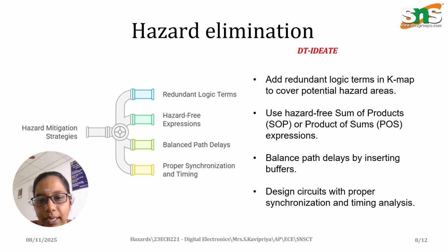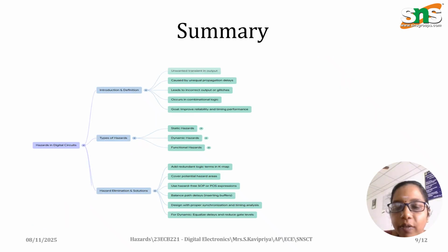By balancing the delays between the paths by inserting buffers, we can eliminate these hazards. And by designing a circuit with proper time synchronization between the input and output, we can eliminate those hazards. We have discussed in depth what a hazard is, the types of hazards, the static and dynamic hazards, and finally the elimination of hazards.